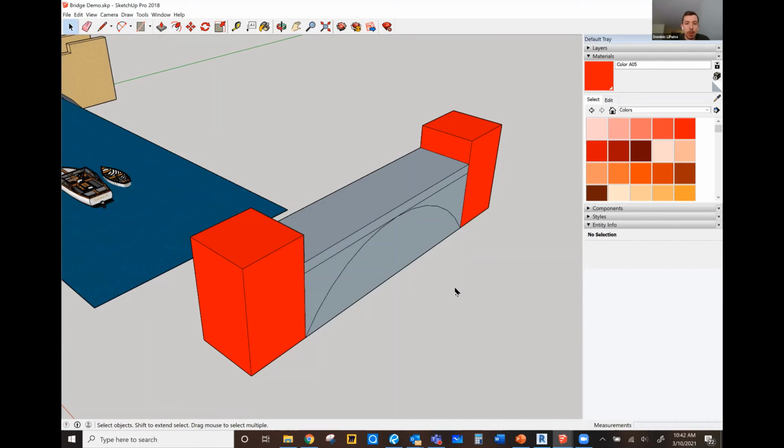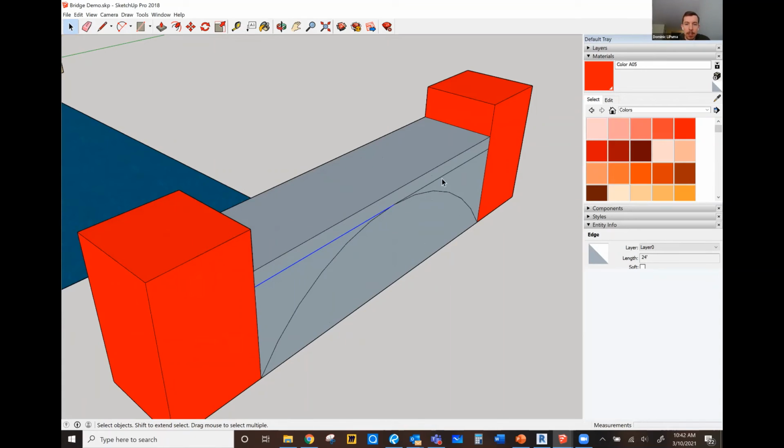And then Megan, correct me if I'm wrong, we're going to start to get rid of the lines that we don't need. Yep. Okay. So you can see all you have to do is click on an element like the line to select it, and it'll highlight it in that blue color. To select multiple things at once, you can hold the control command, and you can see there's that plus sign that's showing up next to my cursor. So if I click on another line, it'll add it to that group. If I accidentally click on something that I don't need, if you hit Control Shift, it'll add a minus sign, and if you click, it'll take that away from the group.